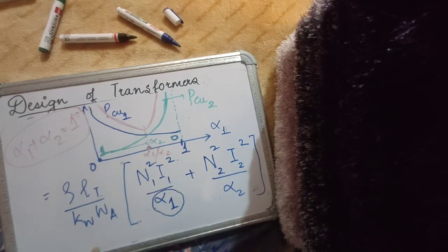So all of these things you have to take into account, such as the core losses, how you allocate the areas. Also, while allocating the areas, you have to take care that the electrical conductor should fit within the window area, so you have to take care of the sizing. That is another equation.